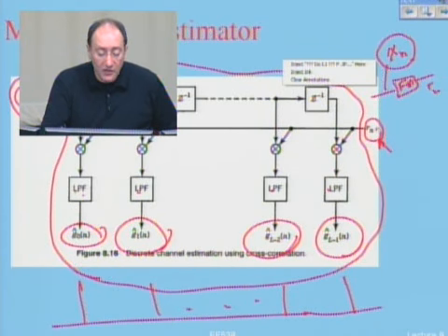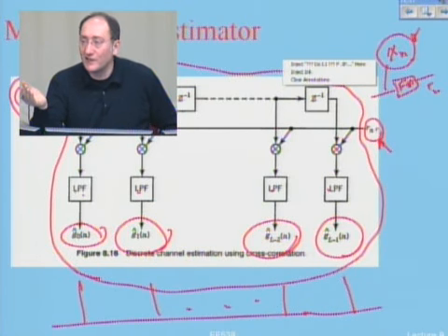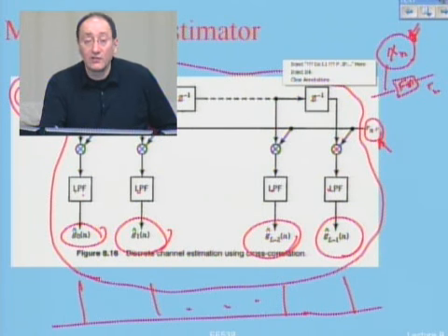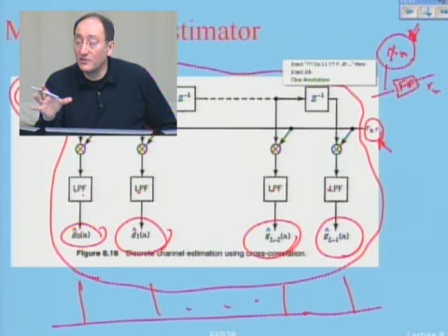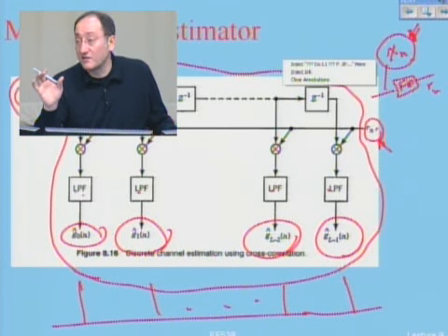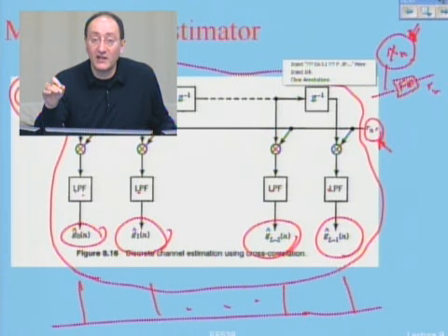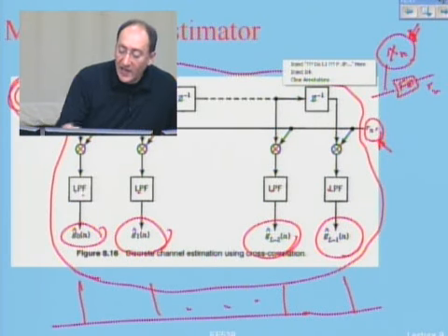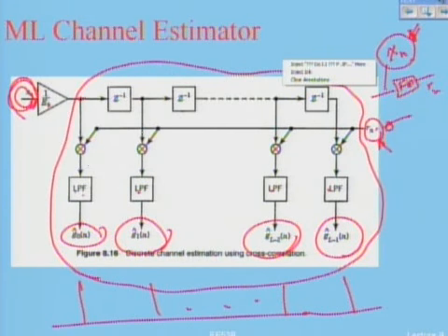But basically what you're doing here is assuming that the transmitted signal is known. But in the real world, I don't know what the transmitted signal is. So how do you do that? I send some training sequence. For example, with a GSM signal, inside the packet they have certain training bits, like 26 bits per packet, which are known bits. And I use those bits to estimate the channel. So I put those in here and the received signal associated with that in here. In this structure, I measure the impulse response. Okay, that's one way to measure the impulse response.